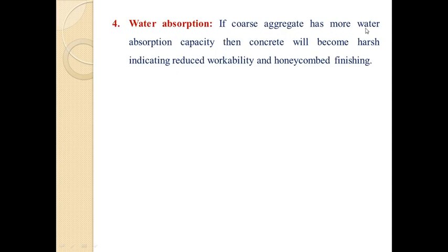If coarse aggregate has more water absorption capacity, then the concrete will become harsh, indicating reduced workability and honeycomb finishing. So coarse aggregate should be selected such that it does not have the water absorption property, meaning it does not absorb water from the concrete. If it absorbs water from the concrete, the concrete becomes harsh, which results in honeycombing of that concrete, and it also reduces the workability of that concrete.